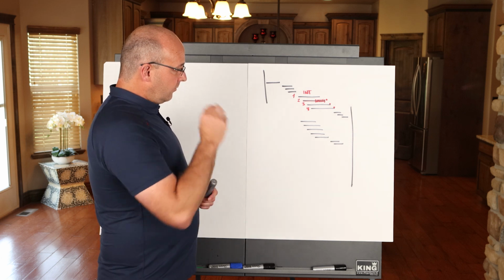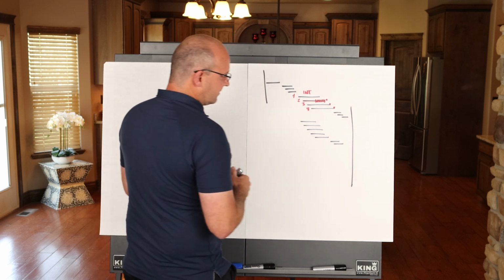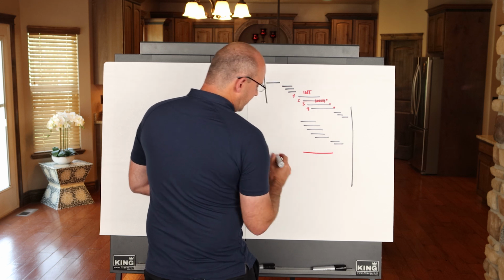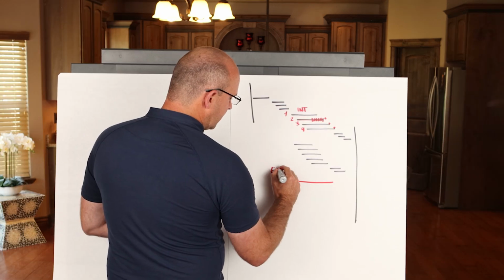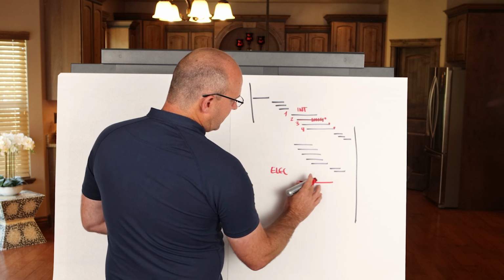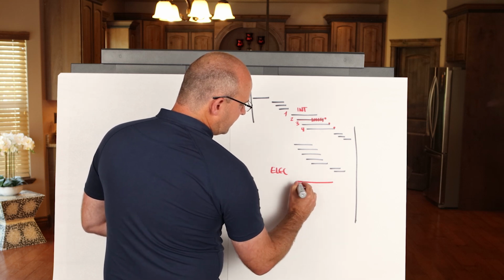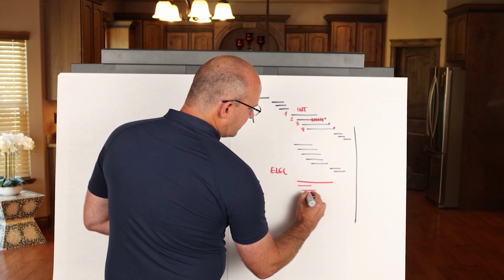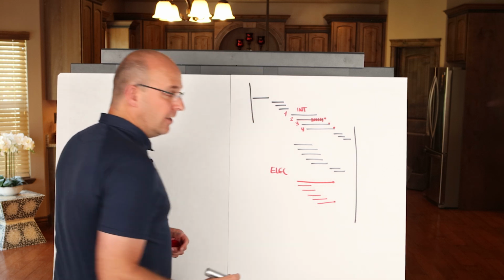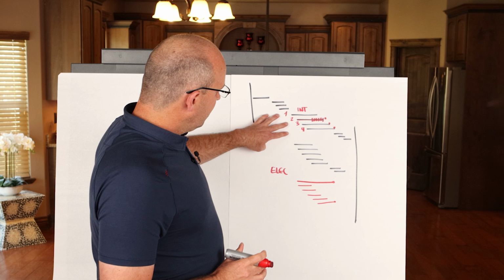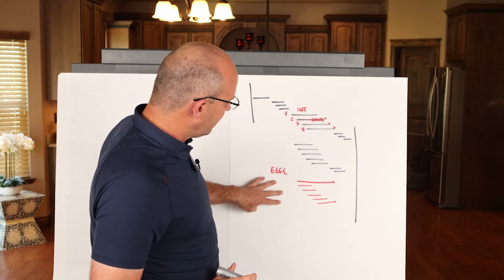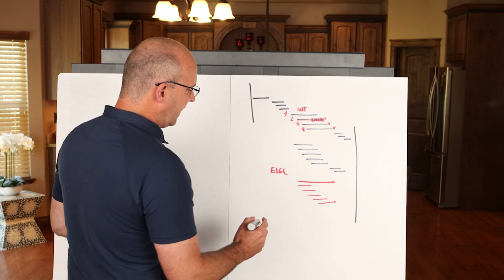Now, I will always make sure that in some portion of the overall production plan I detail out the electrical rooms, okay? And these electrical rooms you can have as one overall sequence, or you can say, hey, level 1, level 2, level 3, level 4, service entry section is complete. But I want to know not only when the individual commissioning activities are ready by floor, but when do I have overall power?